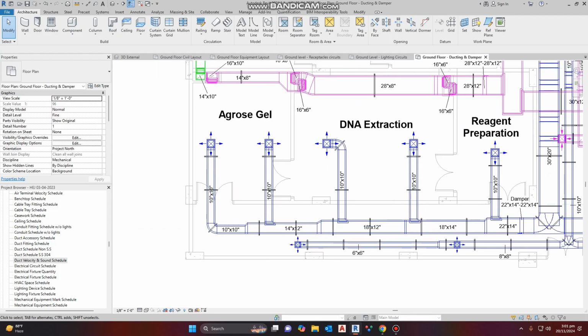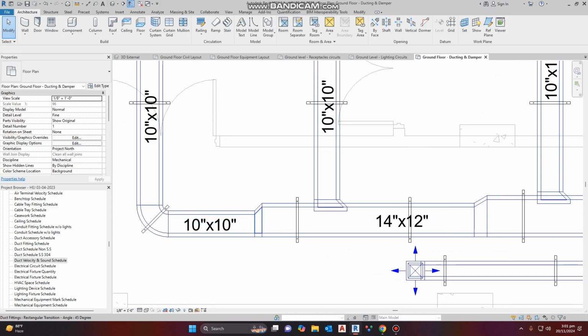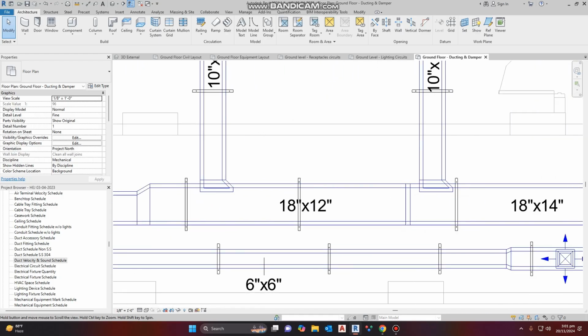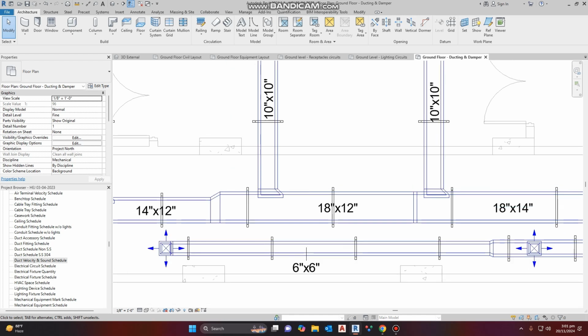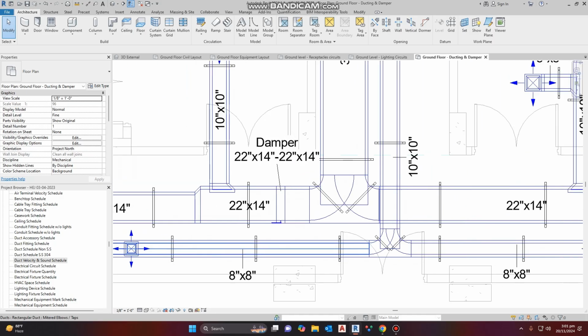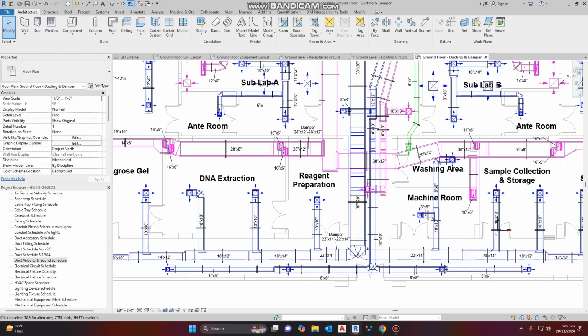As you can see, apart from the ducting and the relevant insulation details, we have also incorporated the duct hangers such as struts, angle irons. This will help us in better clash detection and better execution process.